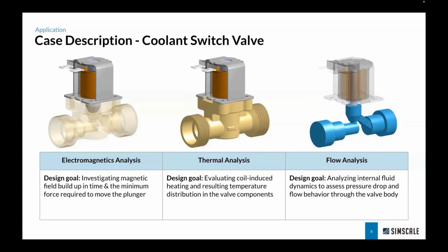And in the thermal simulation, the driving current through the coil is generating unavoidable resistive heating. And in compact EV environments, it's not likely to have active cooling systems. So the solenoids rely on natural convection to dissipate this excess heat.